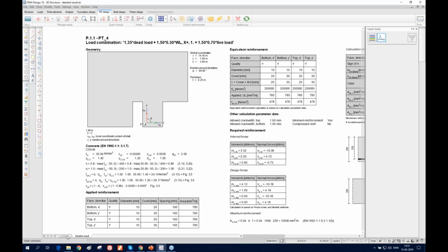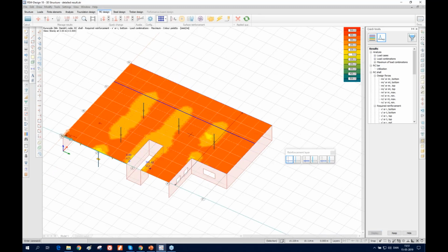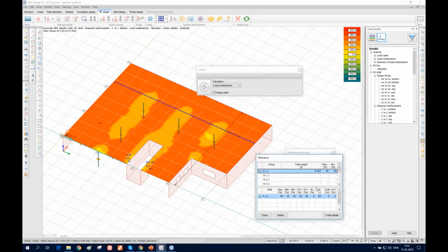So we can go back here. Another feature that's added is this no-shear. By default, this no-shear is on. Previously, if you were designing plate, a lot of these plates showed not okay in the shear capacity.